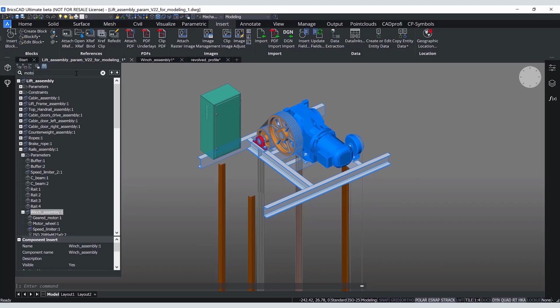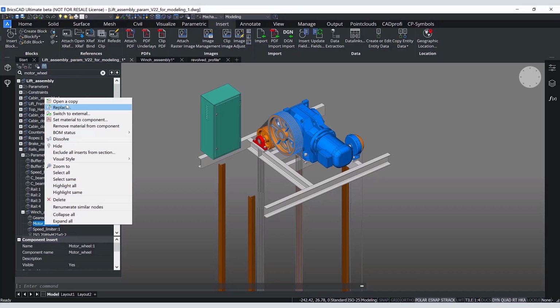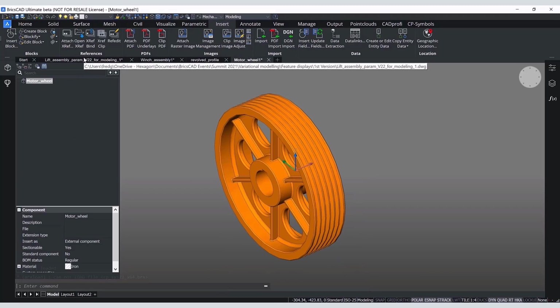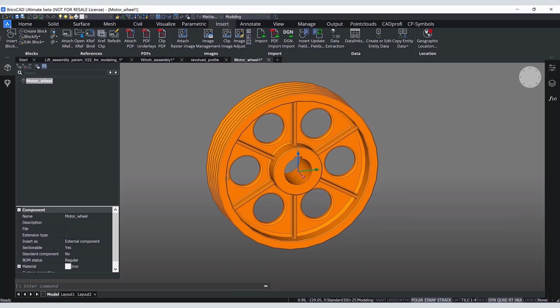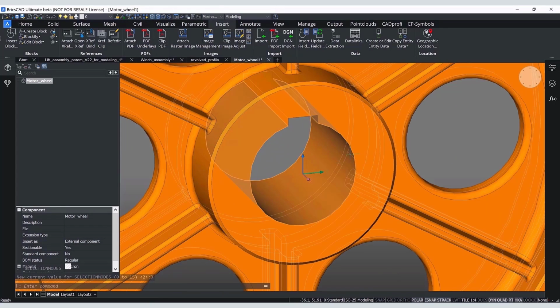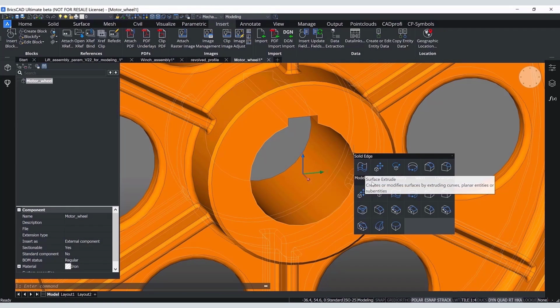As you see, we forgot to add a central hole to our wheels. Do we need to recreate the wheel, again remove existing wheels, insert the new version and change parameters for one of them? No, just modify and reload. First step is to add a central hole. We do not want to draw a new hole, while we can just use the hole from the initial non-parametric wheel.